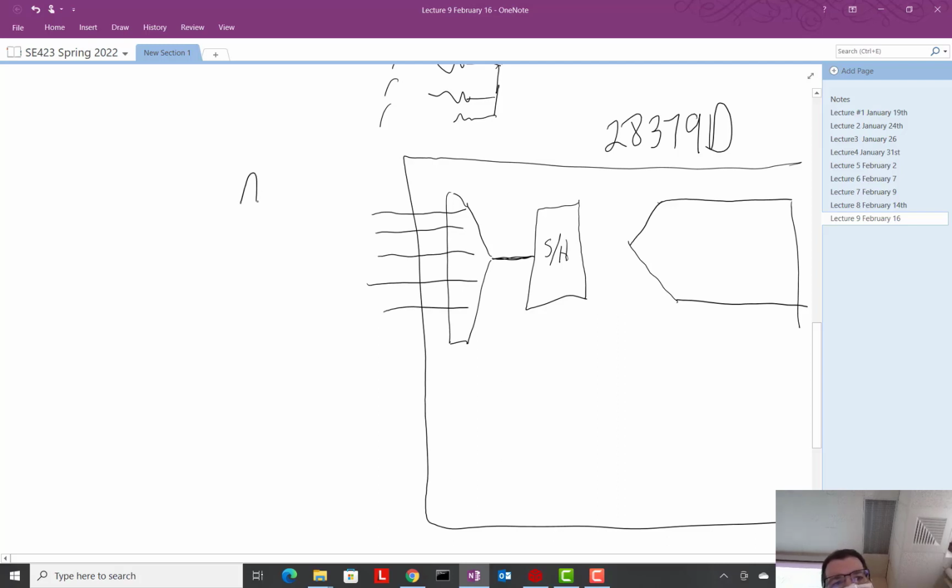They're called ADCIN A0, A1, A2, A3, A4. There's quite a number of them. First a decision has to be made: which channel do we want to sample at this moment in time? Only one of these channels can go into the ADC unit at a time.